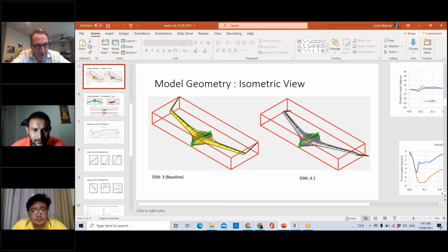I'm trying to remember, Ron, if I had the winglet swept that much, or if that happened after I put together the initial package. I honestly don't recall. It does look like a lot. It looks like too much. I agree. There will be a point at which the wingtip sweep will, of course, work against you, because even though you're increasing lever arm, you're losing lift curve slope because the sweep is going up so high. Yeah. And then elastically,